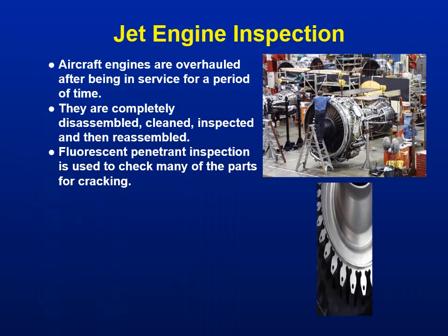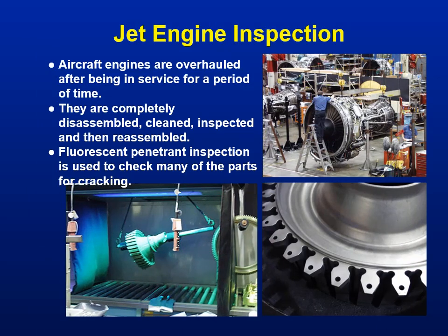Jet engine inspection. Aircraft engines are overhauled after being in service for a period of time. They are completely disassembled, cleaned, inspected, and then reassembled. Fluorescent penetrant inspection is used to check many of the parts for cracking.